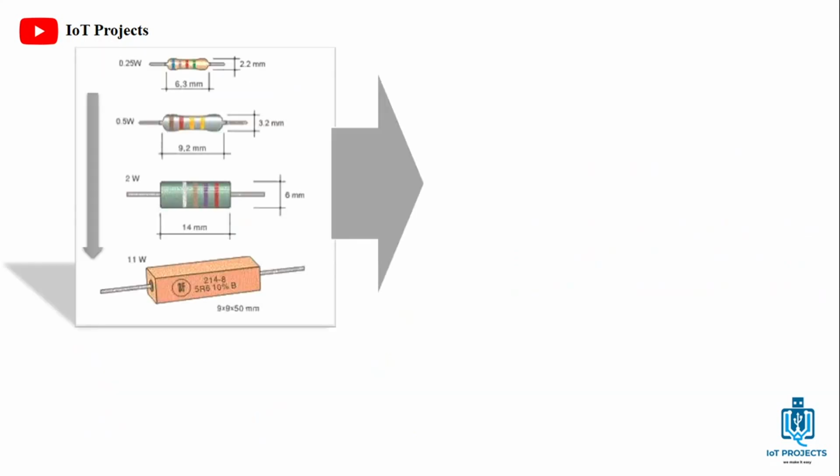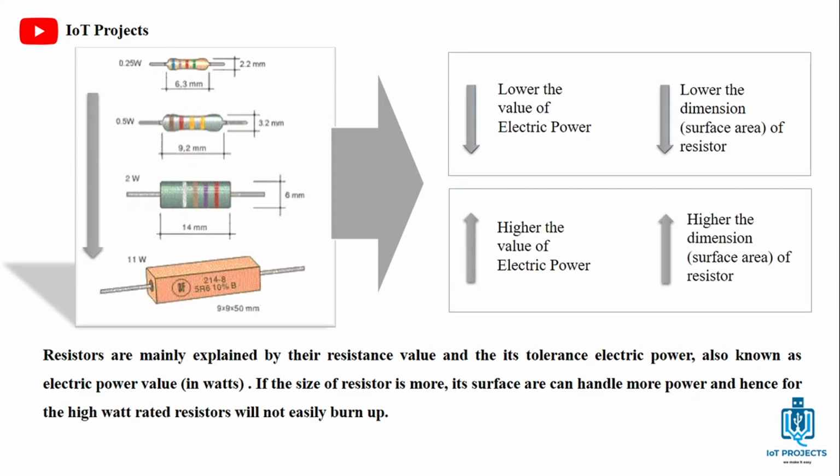P in the previous slide is in watts, so if you know the resistance and either the current or the voltage through the resistor, then you can see if you need more power handling than 1/4 or 1/2 watt, noting that the closer you get to the max power dissipation, the more environmental factors matter: how tight the resistor is with other hot parts, how much airflow there is, how close it is mounted to the board.